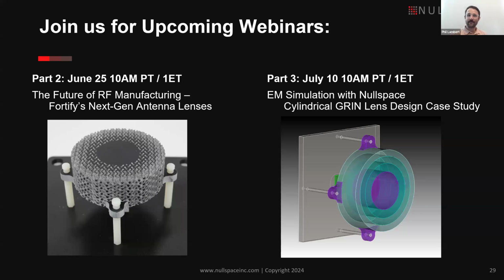One, when we think about the thermal characteristics of a lens, you have to consider the thermal environment, not just from the nearby electronics, but also what ambient environment you are going to be exposed to, and the considerations therein. If we look at the ceramic material as an example, we expect temperature performance to range up to about 1400 C without significant changes to the behavior of the material. We're still working to verify that, but in the ceramic material, we would expect very limited impact of any thermal expansion.